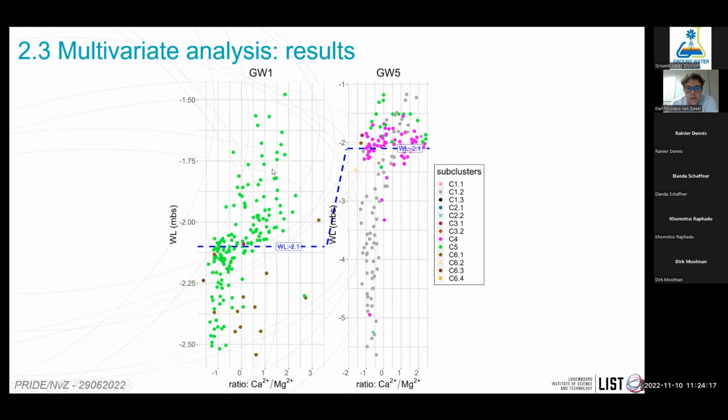And what you can see is that when the shallow well is wet, you get this green cluster, and as it dries out, you get this purple cluster, and if it dries out more, you start having the dominant deeper groundwater that's really in the dense slates. What is also interesting to note is that this validated our hypothesis that we could see preferential flow paths in terms of chemistry. So when GW1 is really dry, what you're really pumping out is just seepage from the top. If there are rainfall events, you see the bypass. So the recharge is not chemically altered by the soils. It just bypasses and gets into the deeper part of the aquifer, or relatively deep, at 2 meters.